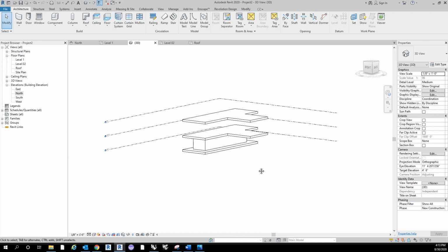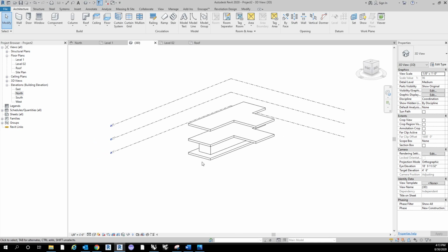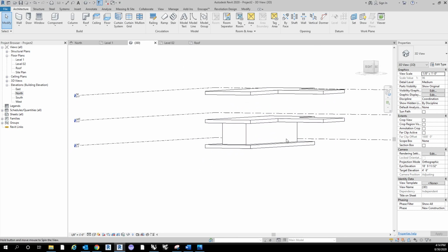Okay. Personally, I like modeling and creating my forms, going back and forth in the 3D view with the 2D views, because it validates a lot of the decisions that I'm making, and I know that the geometry is performing exactly how I want it to. If I was just building this in plan view, it might not show up exactly how I want it in elevation and so forth. So I'll use a combination of floor plans, elevations, 3D views, sections, etc. to go back and forth while working in 3D to make sure that all of the geometry is working how I want it.